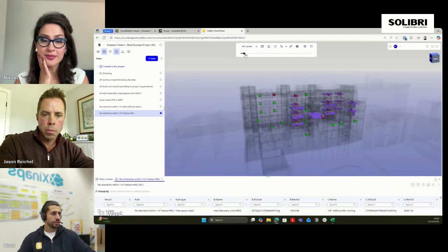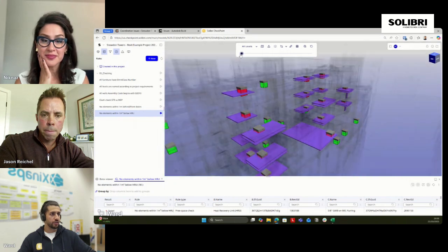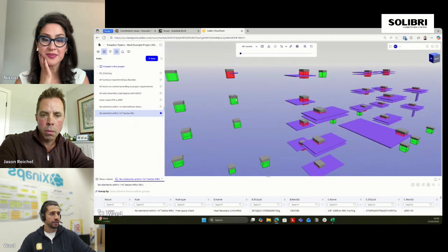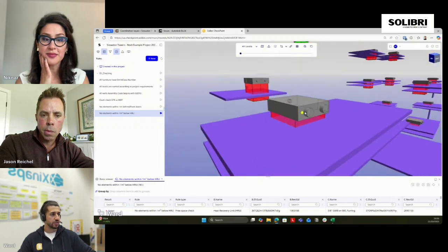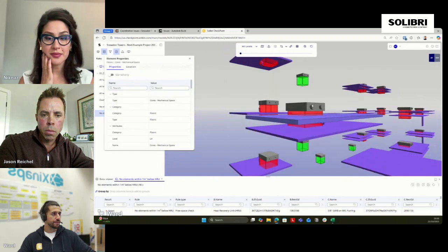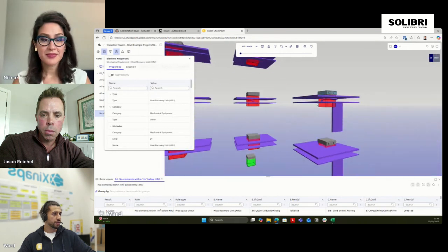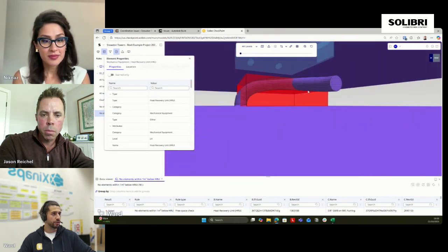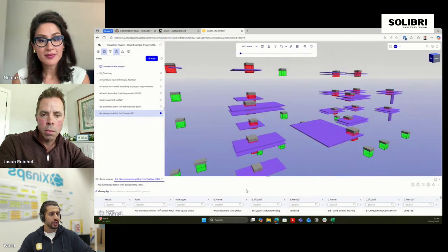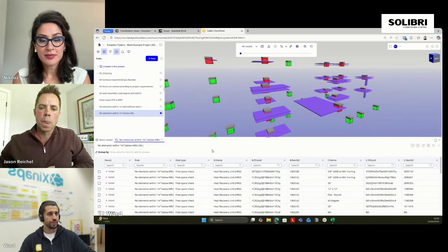So there you go. We have some results. We can run the text view, of course, to show the hidden elements, but let's just keep it this way. You can see for the ones in green, there is no intersection, but for instance, this one, here we have a clash with these floors. This one over here, also with floors, but also a pipe or a flex duct, I think. Yes, it's a flex duct. And we can see the results also in the data viewer. So in the data viewer, I can keep on grouping and so on.